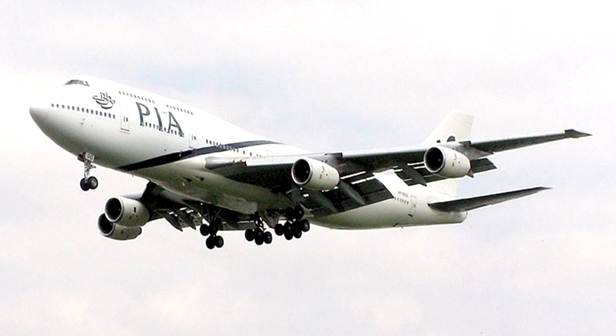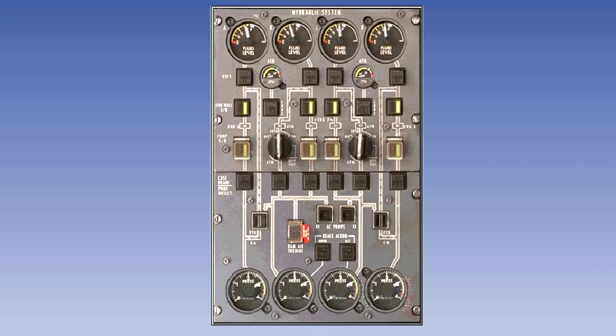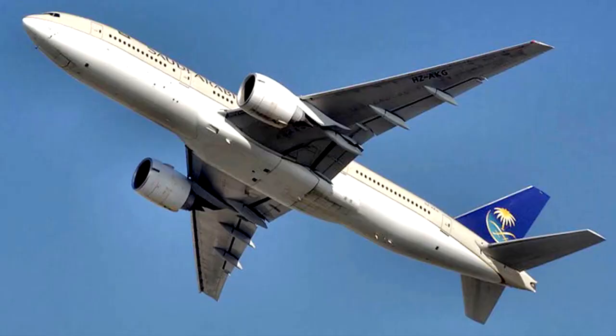Redundancy and backup systems are used to enable continued function after failure of one or more systems. A good example of this is the use of multiple engines. Systems and components are isolated and segregated so that failure of one does not cause failure of another. For instance, aeroplanes are designed with multiple independent hydraulic systems with no transfer of fluid between them. Systems are tested for proven reliability so that multiple independent failures are unlikely to occur on the same flight.